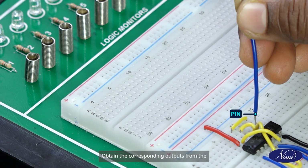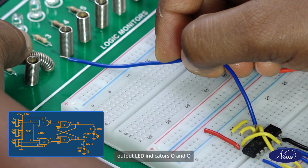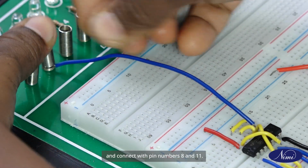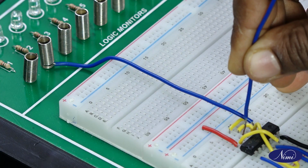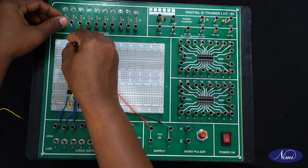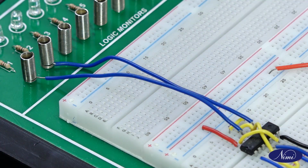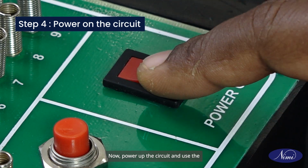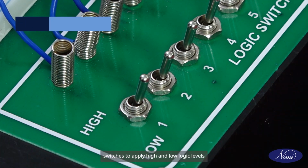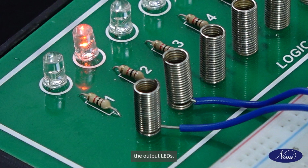Obtain the corresponding outputs from the output LED indicators Q and Q bar and connect with pin numbers 8 and 11. Now power up the circuit and use the switches to apply high and low logic levels to the R and S inputs in different combinations. Observe corresponding latch state changes on the output LEDs.